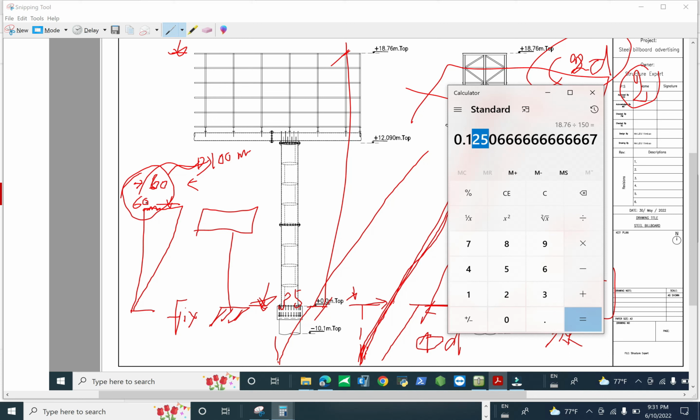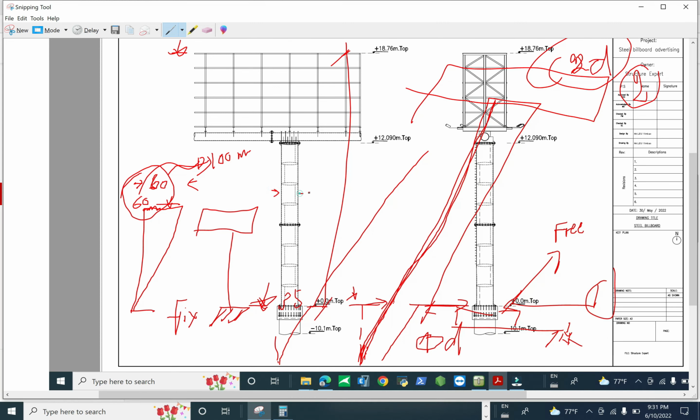When you design with a fixed base, fixed connection or fixed support, you see the maximum deflection is only 60. So you say, oh, it's a very good design, so it's acceptable, and you can minimize it by using this tube smaller and smaller. In this case we use this tube of 1.2 meters. You can minimize it to 0.8 meter. It also passes.